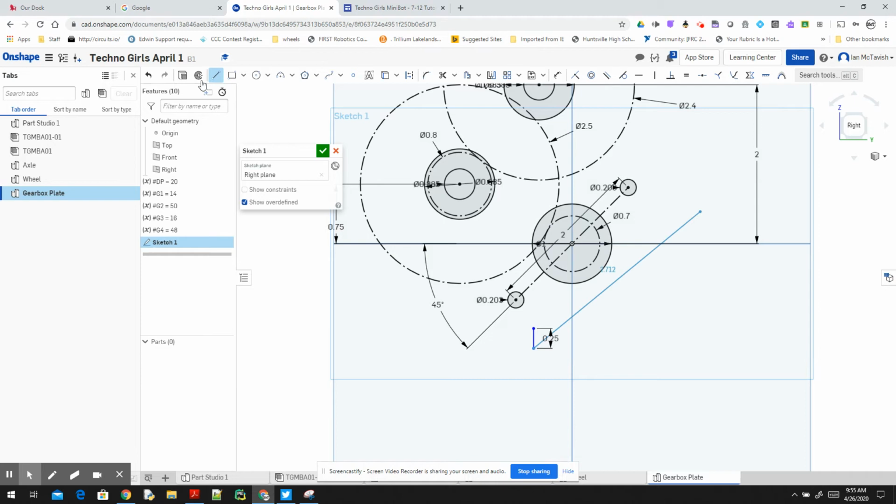And so what I'm doing is I'm going to create a slot. Instead of a hole for the screw, I'm going to give it a slot. And that allows me to do slight adjustments in the positioning. So I'm going to set the distance from the axes. So there's the dimension tool. And what I'm going to do is click the horizontal axis and the top of this line. And I'm going to click and type in 2.52. So that's the diameter of the Minisim. So half of that is the radius. That's what I need to deal with.